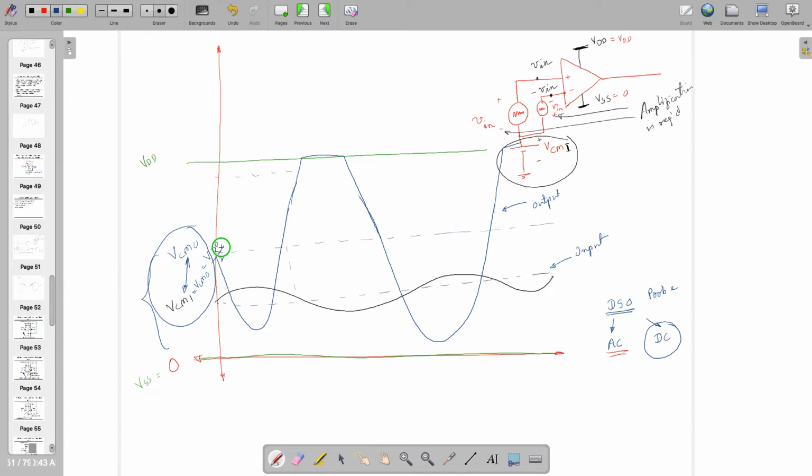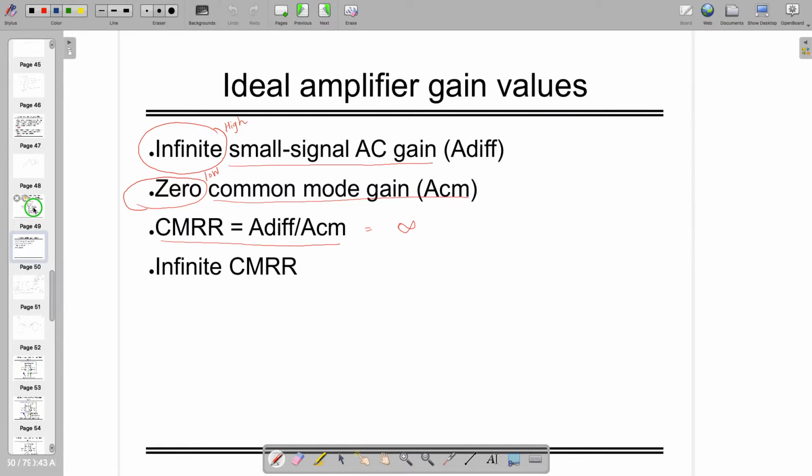The most happy guy, because there is no fluctuation from input common mode to output common mode. But that's not possible. There has to be some number. So that's why I'm saying I'm expecting to have the common mode gain as low as 0, but there'll be some gain, right? So notably, this gain might be like minus 6 dB or minus 10 dB or something like that, or sometimes a little bit higher than 0 dB. So it depends on your circuit.